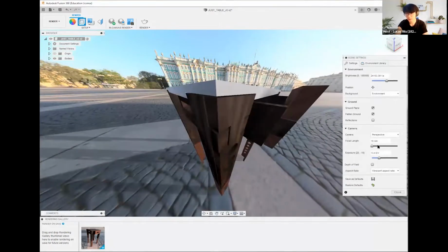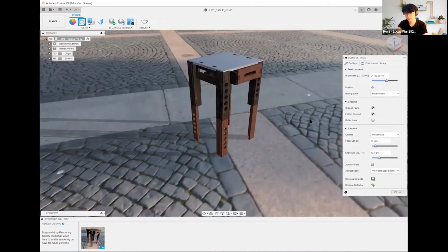So the perspective lens helps you get a much cleaner and more realistic look. And you want to make sure that you use that, unless you have certain cases where, for example, say you have a part of your trophy that extends out and ends up right in front of your camera. You might want to adjust either your focal length or try it orthographic. But in this case, this is something that you typically want to try and play around with.